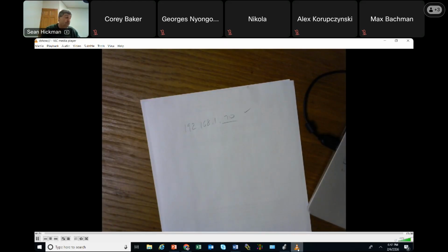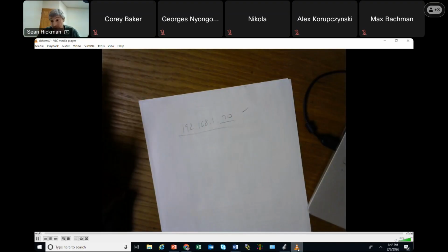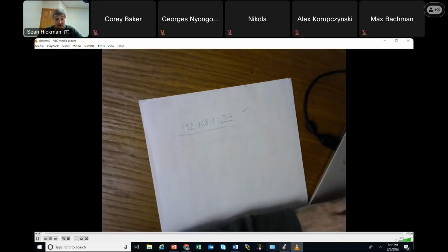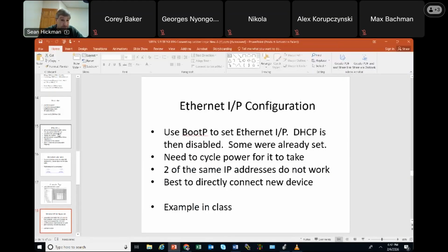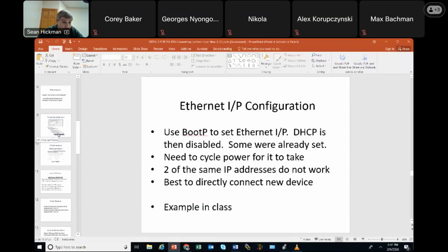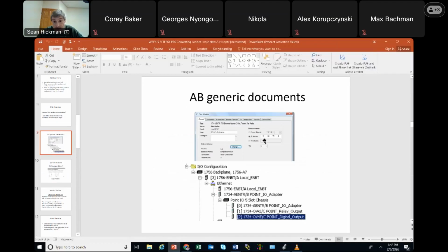The problem is that's just one network. There's a lot of people that use a lot of other networks. As a matter of fact, I just showed you a minute ago where they were setting something up, and it was on a 10.88.70.2 network. Well, that is not a standard factory default network for Allen Bradley, okay? And so if you do want, let me write that down,